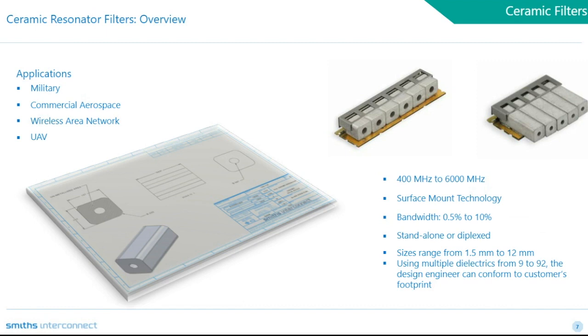Ceramic filters are an excellent choice for RF designers as the perfect moderator between other topologies. While offering lower cost and better performance than most discrete solutions in the same frequency range, they actually maintain the same or even smaller footprint. They will not be able to compete with the performance of a high-Q cavity solution. However, they will be a fraction of the size.